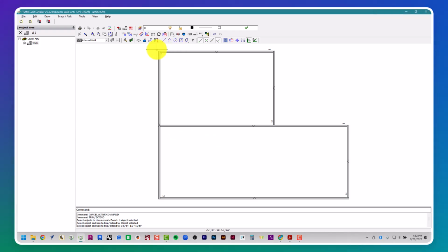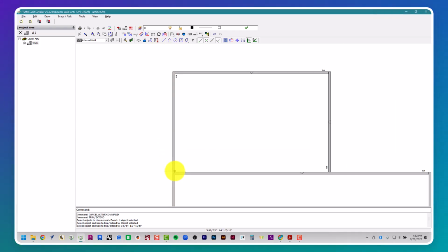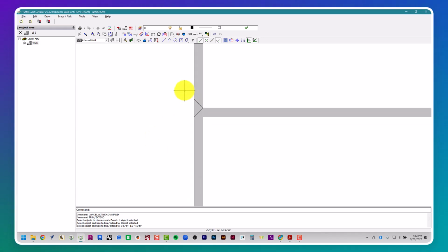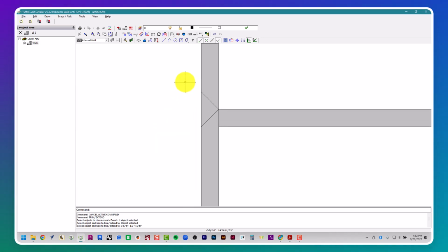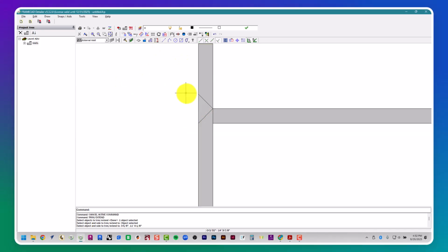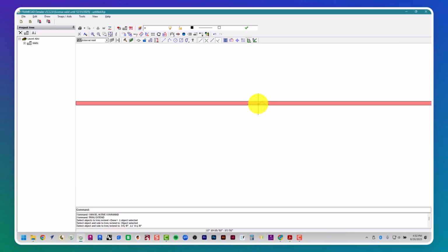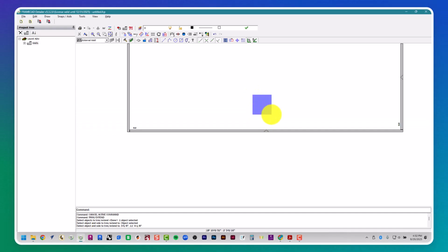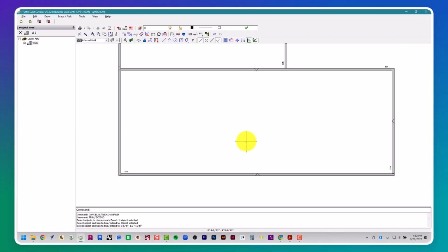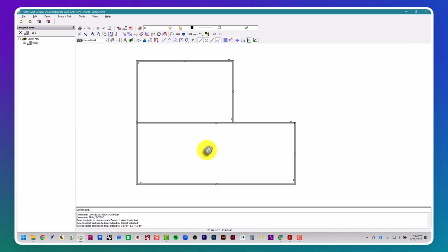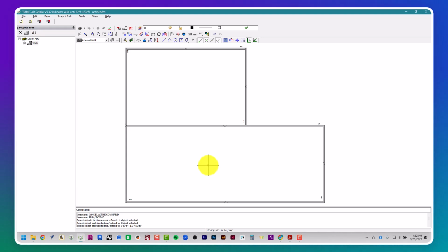Okay. And then let's look at this wall here, EX1. So the reason why I wanted to draw this all in a counterclockwise orientation is because when I'm looking at EX1 as an elevation, when you see this arrow pointing to the right, that means you're standing out here looking to the right and looking at that wall. Same thing when you're looking at this one here, means I'm standing out here looking straight up at that wall versus me standing inside of here looking at the wall from the inside. This has to do with the elevation, so let's not worry about that for now, but we'll revisit that idea later on.